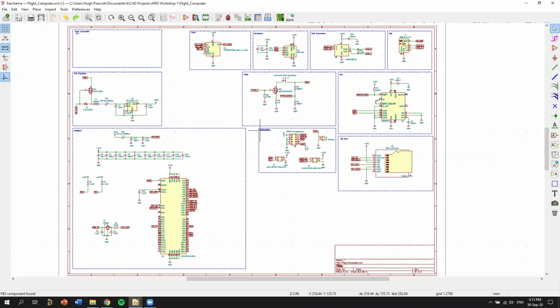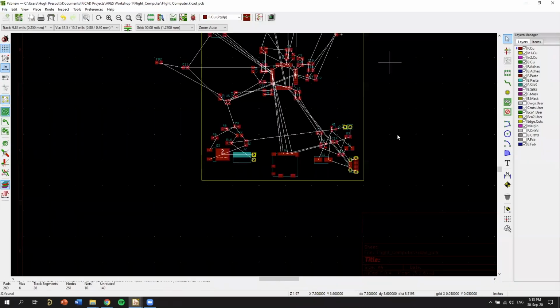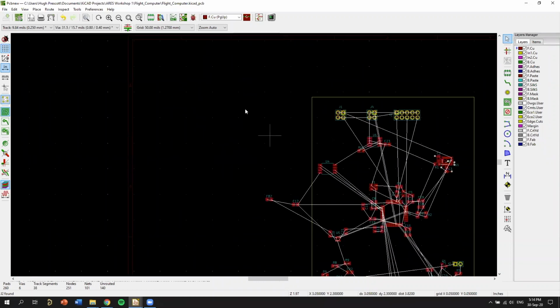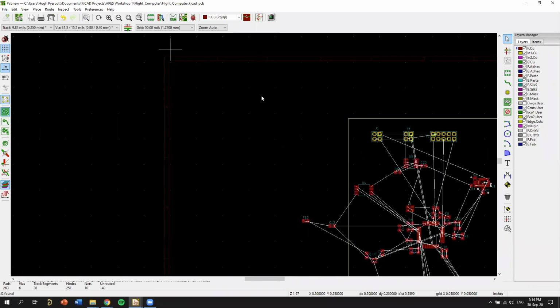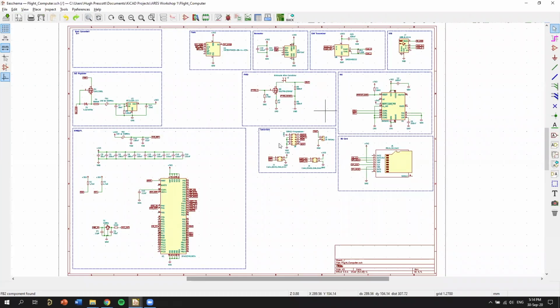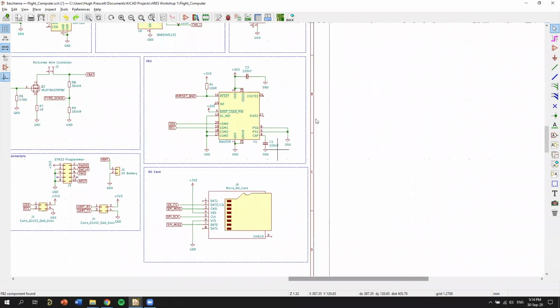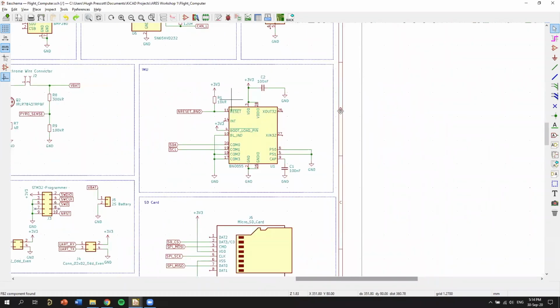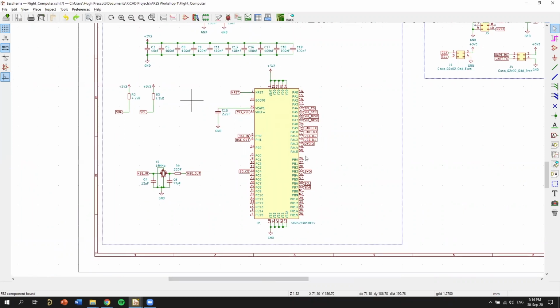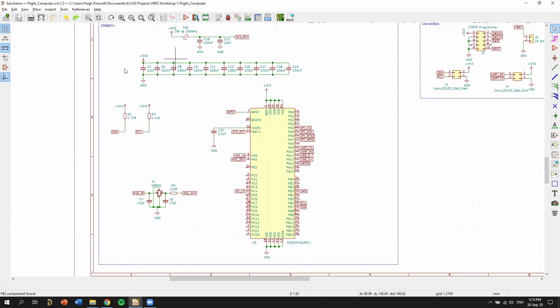And this week, I have a few people join now. Cool. We're going to get about routing it. And so I think last time I just had a big mess of components out here. And I was like, all right, the first step that you need to take is to organize all of the components basically into their schematic parts. So here, we're going to take our microcontroller and then make sure all of the relevant parts that are going to be close to it, like decoupling capacitors and all of this, just group them all together.